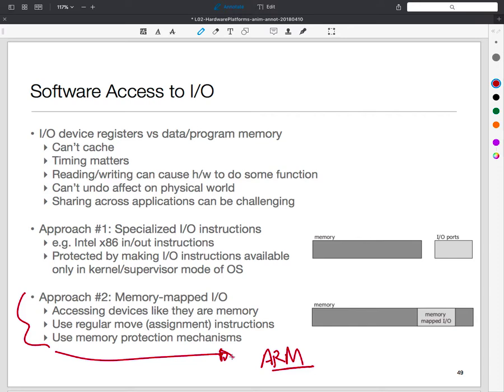So the advantage of this is that, let's say I have some device, let's say a radio, which offers me a bunch of registers. I can map those set of registers into a C or C++ data structure, and then just read and write to it as if I might read and write any other data structure in memory, except that in this case, reading and writing to those locations will have the side effect of working with my radio. So it gives a cleaner way of programming these devices.